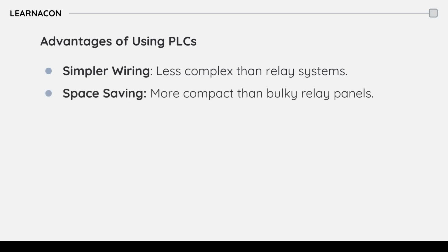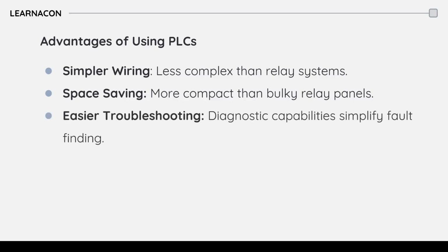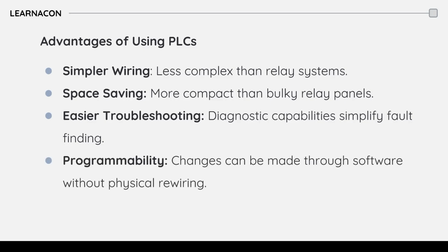PLCs are much smaller than those big, bulky relay panels. This means you have a lot of space and you can use control cabinets more efficiently. PLCs come with built-in diagnostics that makes finding and fixing problems a breeze. No more manual checking like with relay systems. The best part about PLCs is that you can make changes through software. No need to rewire anything. This makes updates and modifications super easy and cuts down on downtime.